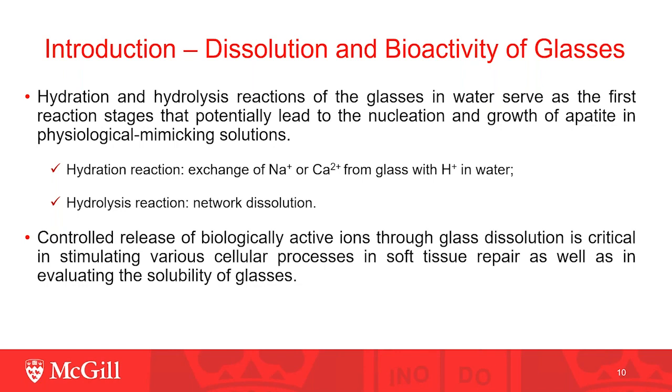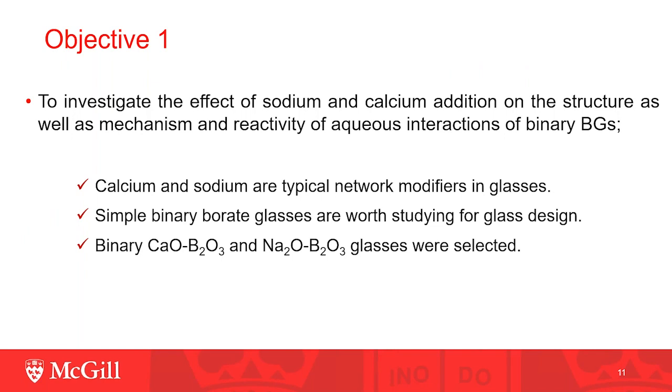Therefore, it is important to understand the glass dissolution mechanism and to study the effect of modifier addition on their aqueous reactivity and reactions. Therefore, our first objective is to study the effect of sodium and calcium addition on the structure, as well as the mechanism and reactivities of aqueous interactions of borate glasses.